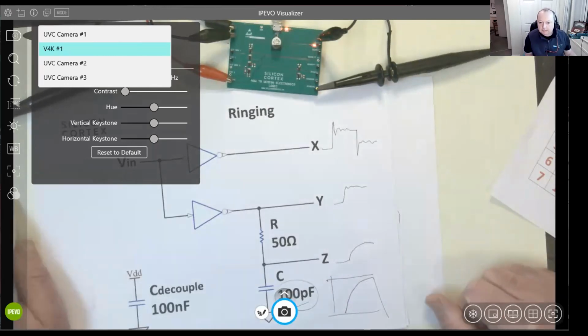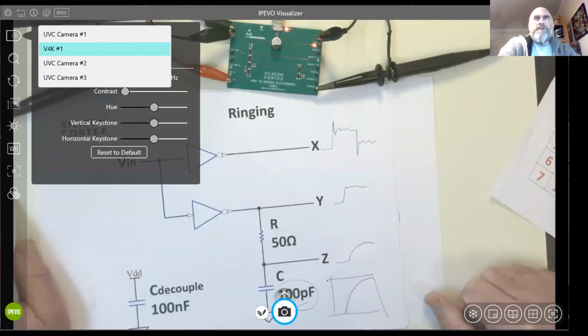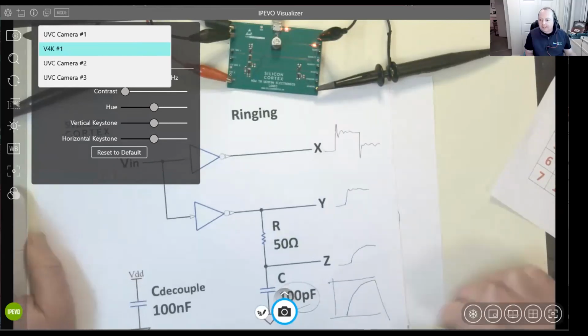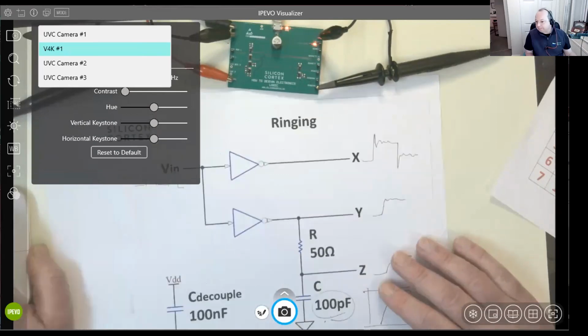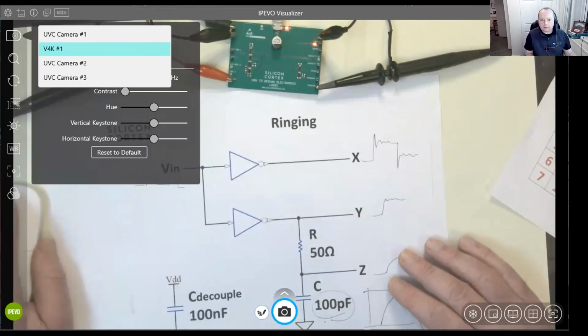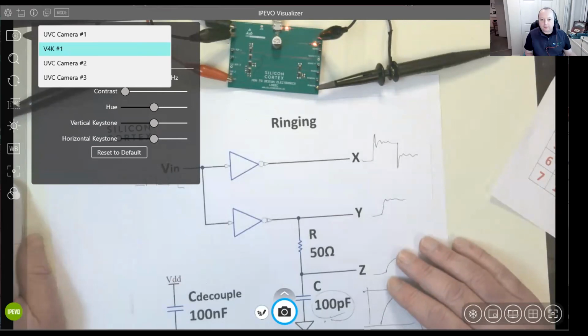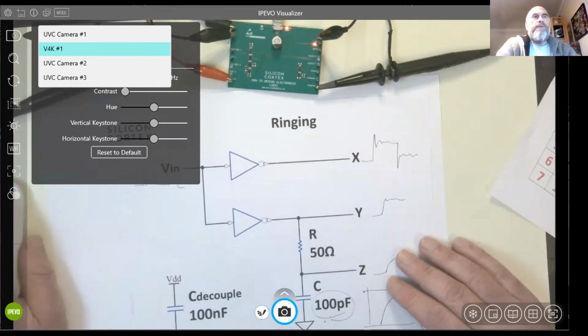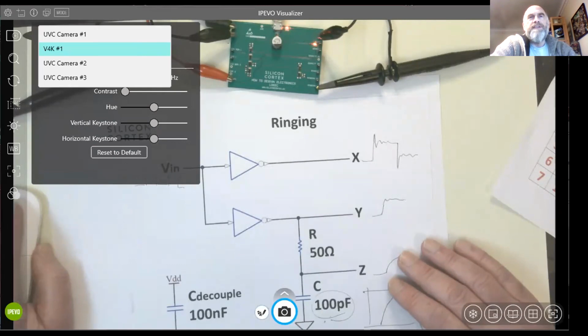Yes, because the line is going to be about 10 meters long, running from the garage to the vehicle. Yeah, you're going to have a problem. Be hit by lightning. You can't run I2C over that. Oh no, but this would be from the vehicle to the box which contains the Pi, the power supply, the ADC, and everything else.